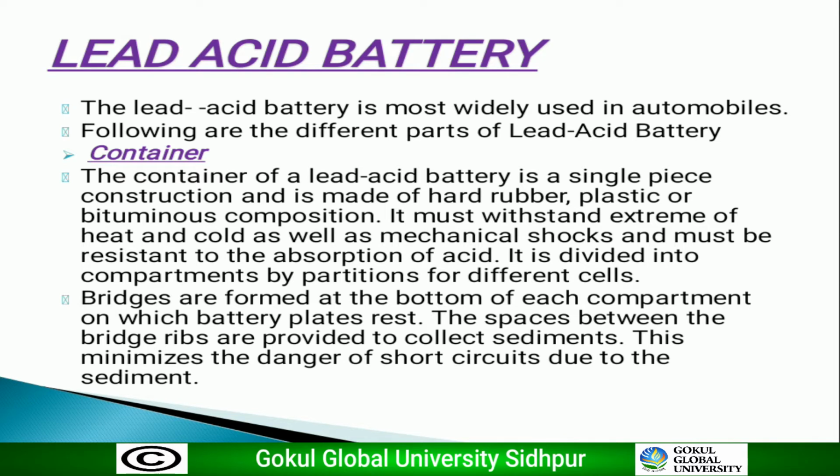This mechanical shock comes from automobile engine vibration, transmission vibration and vibration of different other parts, which also comes when the vehicle runs on the road, from bumps, sudden acceleration and sudden braking. The container must be resistant to all of these mechanical shocks, and it must be resistant to the absorption of acid. As I said, this acid, sulfuric acid, is a highly active material.